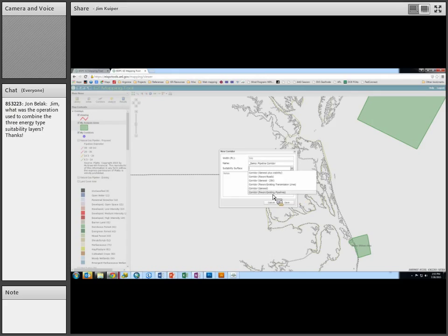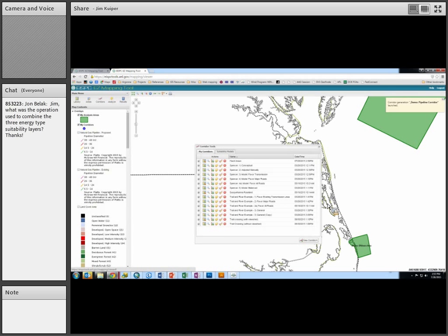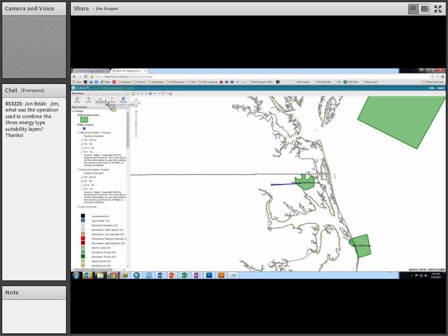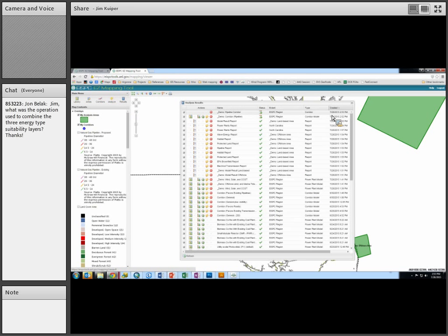These are the default models, so I can pick the existing pipeline model, and when I click Save, it launches that corridor. So I didn't wait for my corridor model to run because I knew there was already a default model that I could use as an input. If I wanted to make revisions to the default model, then I would run it myself before I ran my corridor. But the corridor run already finished, and now the model did as well.